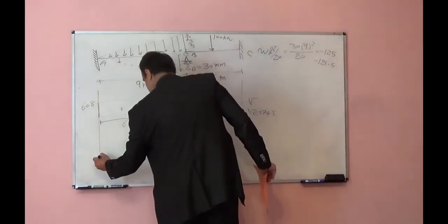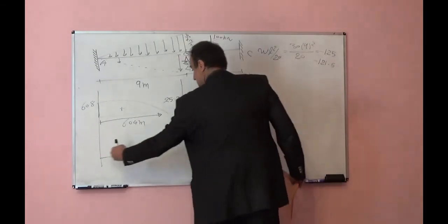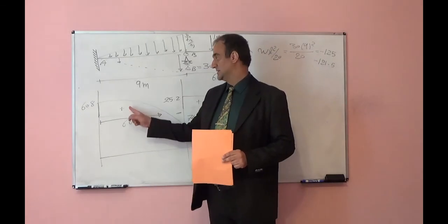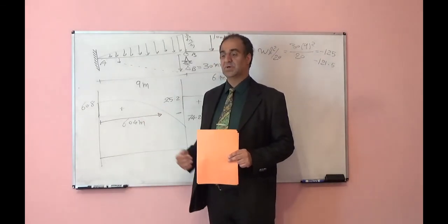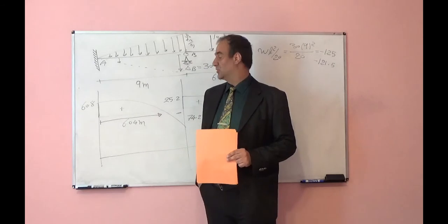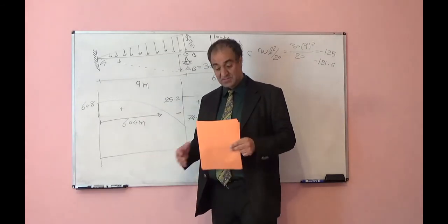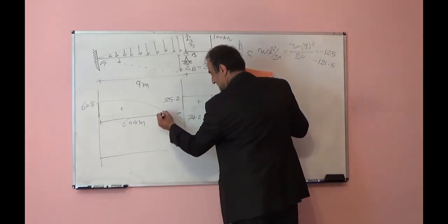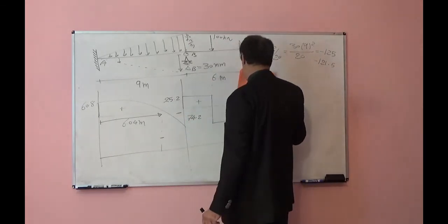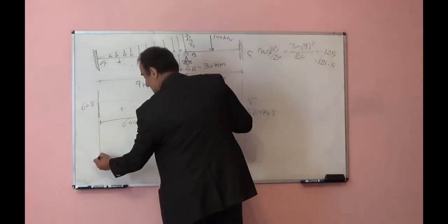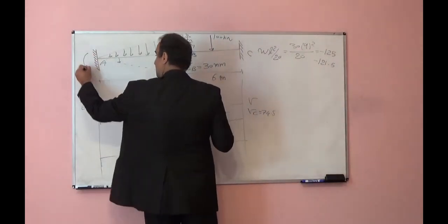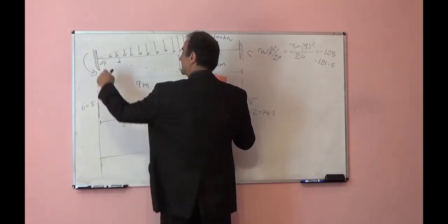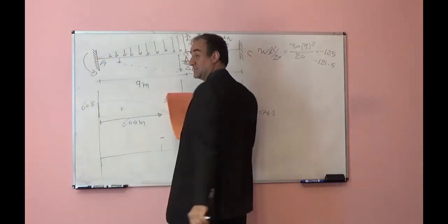Bending moment diagram. In this region it should be a curve shape and cubic, because the shear is, for example, x squared. It is a square shape curve. This will be a cubic shape, and at the location where shear is 0, this should reach the maximum. Here, if you apply MAB and it is counterclockwise, it creates compression underneath the beam.